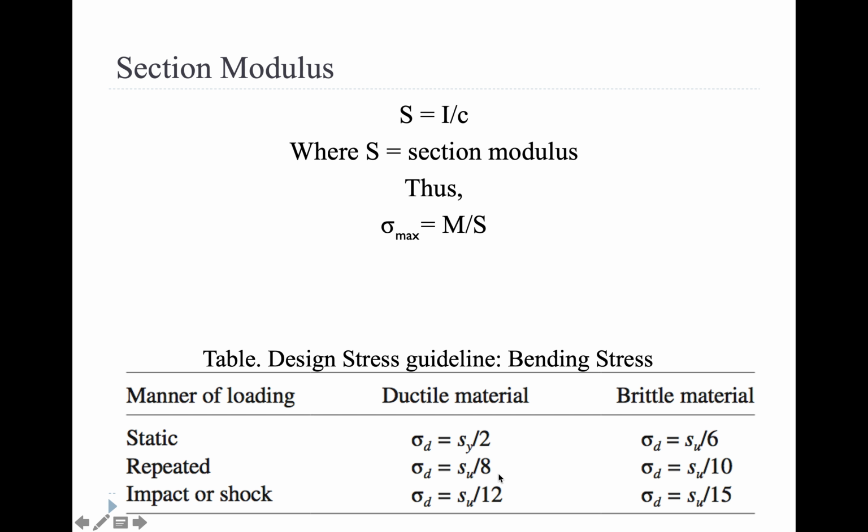Okay, we know a certain material is going to start to yield at, say, 50 ksi. Well, do you want it to load to 50 ksi or more? Well, no, it's going to start to fail and people could die. So designers choose a number so it's never going to get that close. Okay, which they're going to only design to up to maybe half.